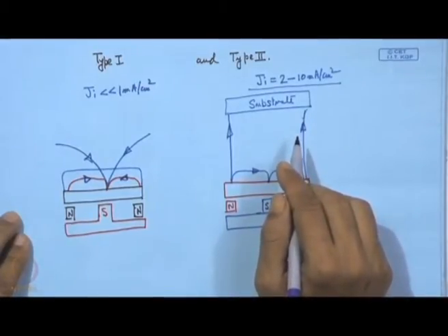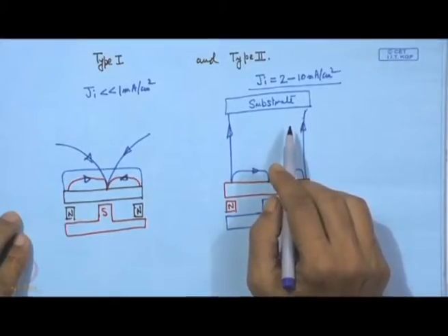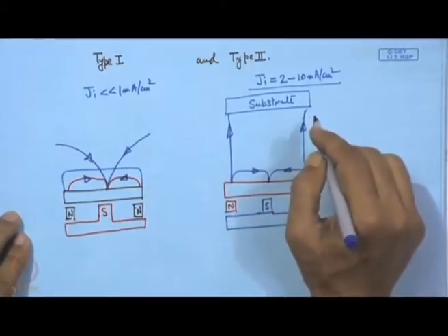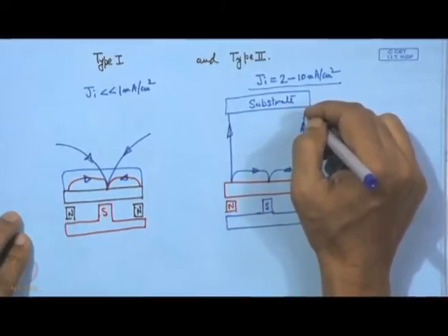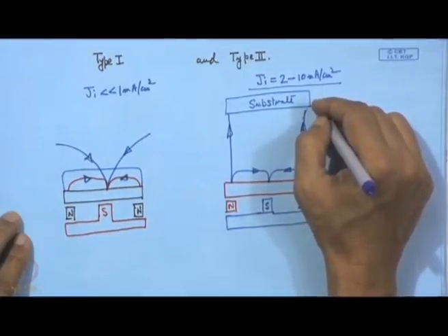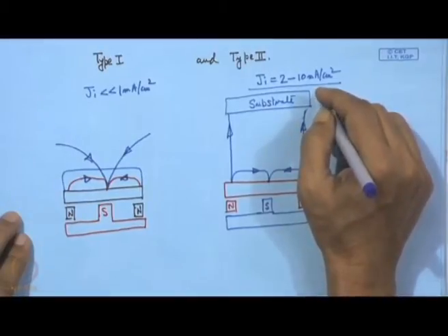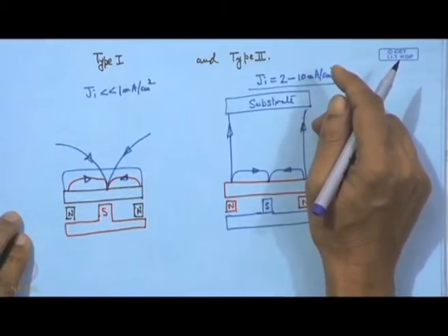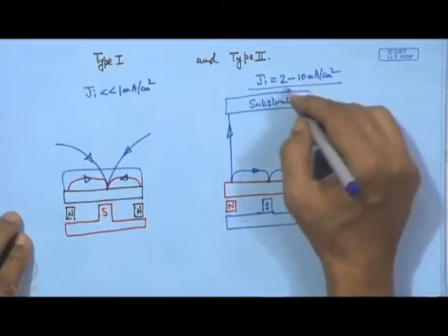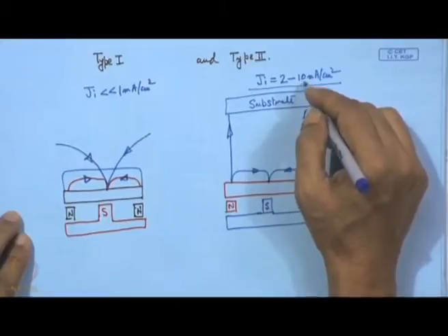This is one of the greatest advantages when we need densification of the coating on the substrate, without much increase of the substrate bias, thereby avoiding incorporation of substrate defects on this surface. At the same time we can have densification of the coating with a high value of ion current density.